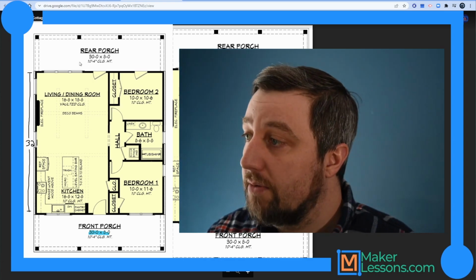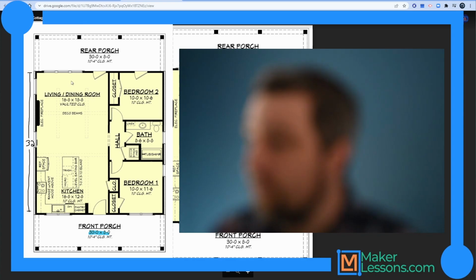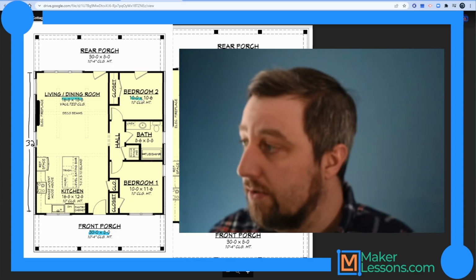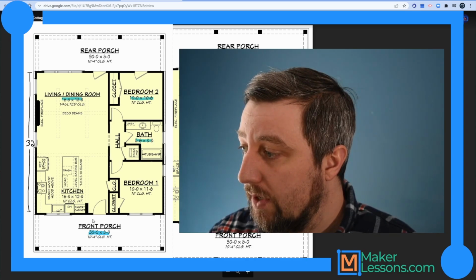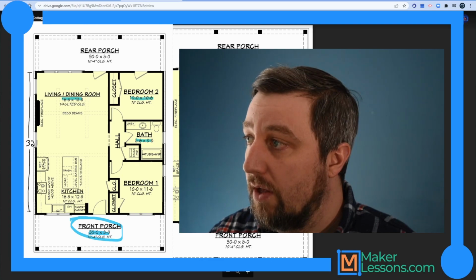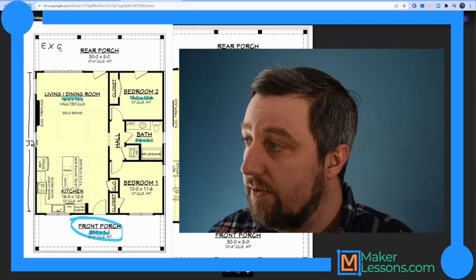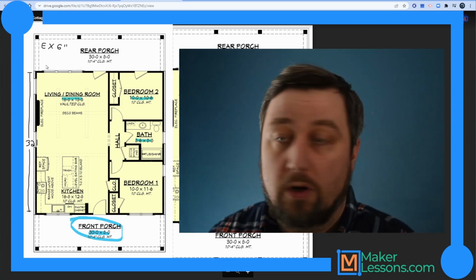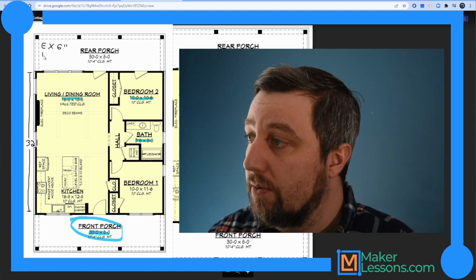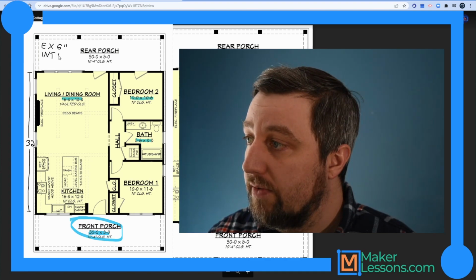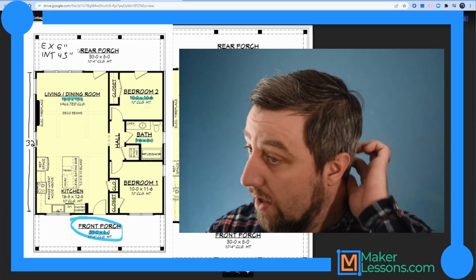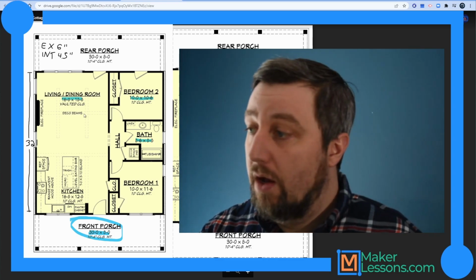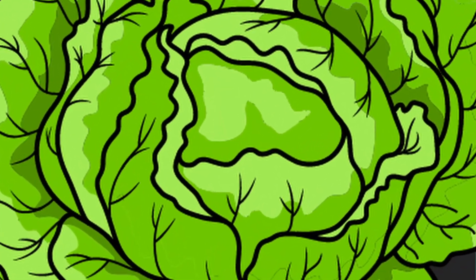All right. We're also going to make some assumptions about wall thicknesses. Reason being, these values here are interior dimensions from inside wall faces, while something like these down here is exterior, right? So we're going to make the assumption that exterior walls are going to be 6 inches thick, and we're going to need that for drawing our floor plan. And our interior walls are, let's say, 4.5. These aren't exact to construction standards, but they're good enough for what we're going to be doing today. All right, so let us begin.